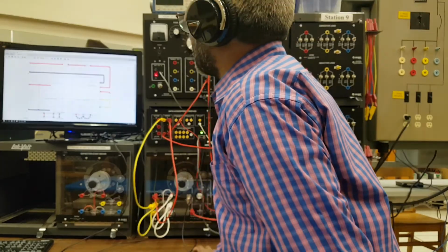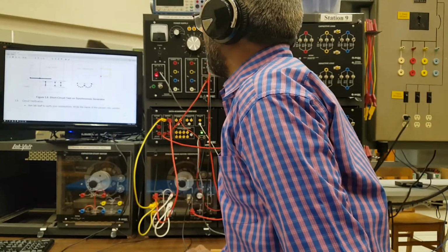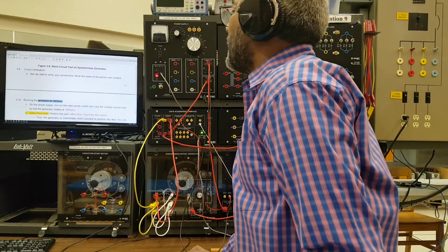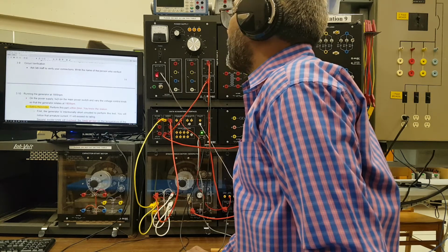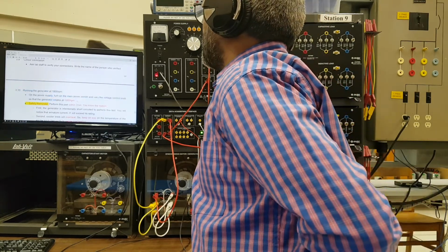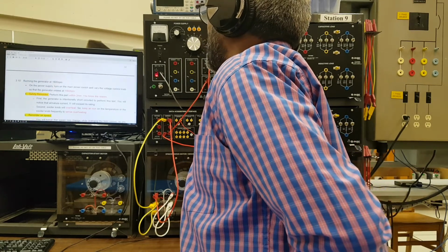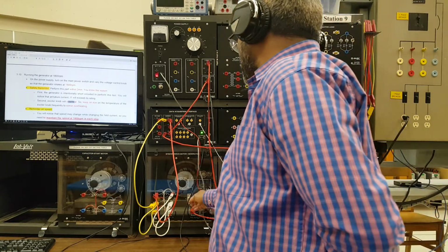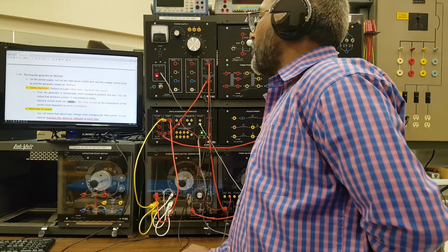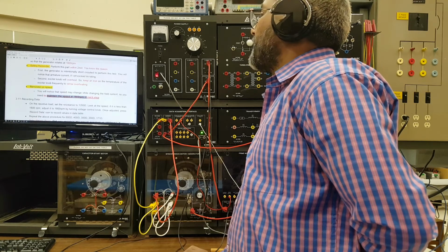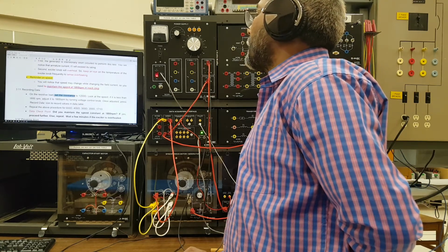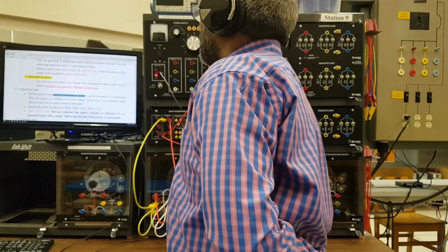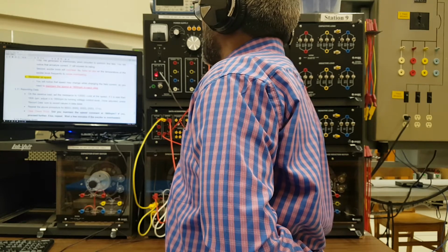So that is the circuit setup here, and then verification is already done, and then running the machine at 1000 rpm again, and will maintain the speed constant. And we have to do this very quickly, because it is a short circuit test, and we will also check for overheating. So we'll maintain the speed constant. So we'll set the resistance to 1200 first and take the recording, and then the speed, and you have to take the remaining things.